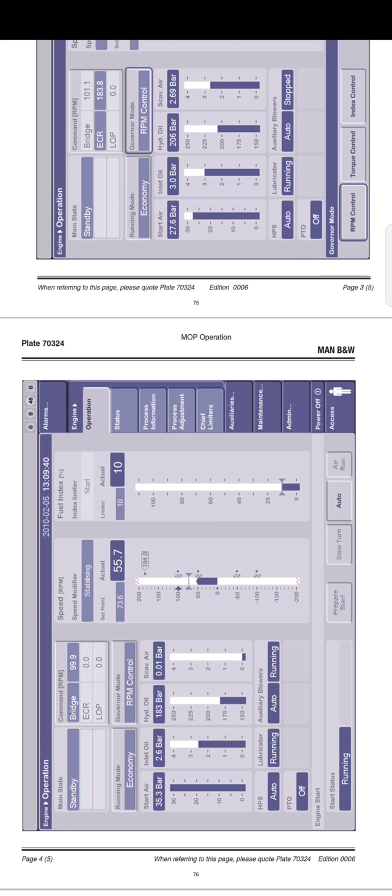Then we have the slow turn button. Manual slow turn is used during preparation before the start of the engine and is normally to be used with the indicator cocks open. Slow turn is used for visual inspection of the blowout. When the button is selected, the engine is operated on starting air through the slow turn valves as long as the control handle is activated. So as long as you press the slow turn button, the engine will slowly turn and you can see any liquid coming out from the indicator cock.